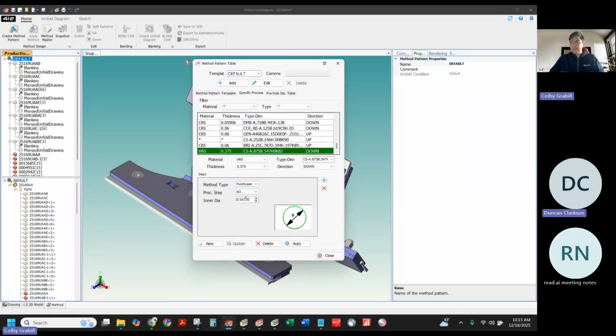So let's say it's supposed to be some other diameter. You would enter in whatever diameter you want it to cut when it sees that feature. So in this case, if we had a hole that was modeled at a certain diameter, but we actually wanted it to be more of a clearance hole, even though it was modeled with a slightly smaller diameter, we can modify that at this stage. So any feature or geometry that comes through, we can have it auto manipulate it with this tool.